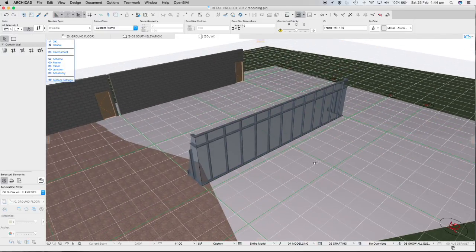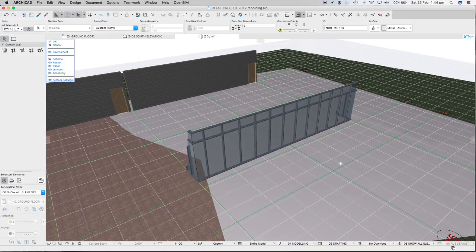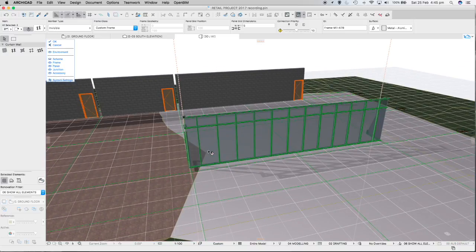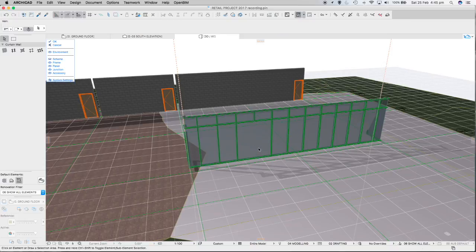And okay, so while we're at it, we might have a look at a door arrangement here. If I leave those 2.5 panels and then put 2 in, yeah, we might do something like that. So if we left 2, we've left 1, 2, 3 mullions in place, but select this mullion here, oh no, just that mullion, and delete it, and then do the same from the other end. So 1, 2 whole panels, and then maybe this one, and delete it. So that gives us 2.5 panels on each end and 3 in the middle.